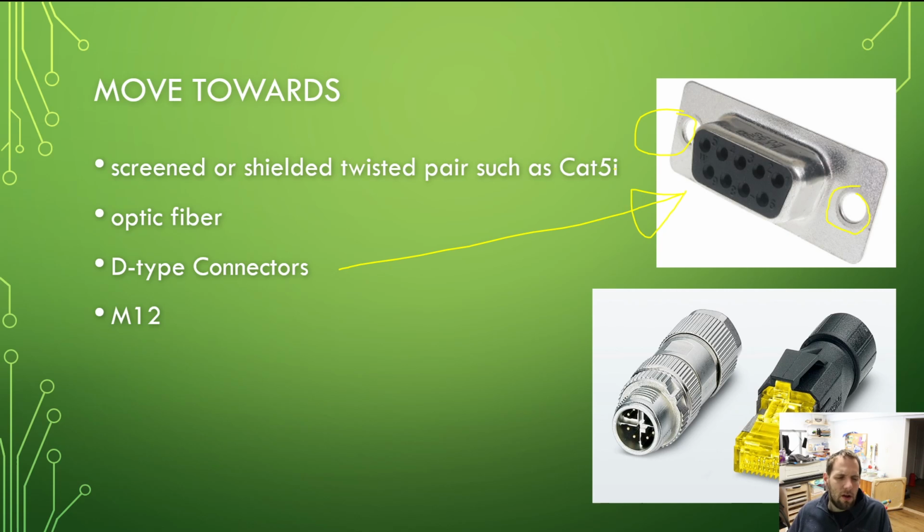It's like, well, we're going to use Siemens-based PLCs, and they're going to use the D-type connector for their Ethernet, or they're going to use this M12 form factor. All right, so M12 is what you're seeing right there on the end. That's just showing it next to an Ethernet cable for you by size. These DB9 connectors, maybe the Ethernet cable or plug would be from that point to like that point or something. They're a little bit bigger, those DB9 connectors.